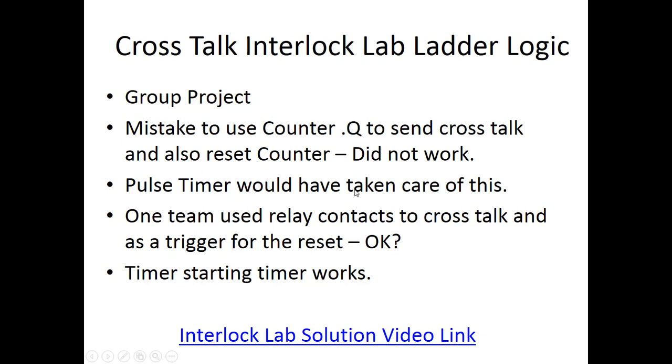Using some type of a pulse timer took care of resetting of the timers, because a lot of times you wanted to signal the other controller, but you didn't want to keep something held on, so all you would have had to do was make the pulse timer true briefly. Then, when the counter gets done, all it's got to do is for one scan make that pulse timer true, and then that pulse timer would pulse over a quarter second to hold that relay down, if you can imagine that, and then you could reset the counter and the pulse timer would die after the quarter second.